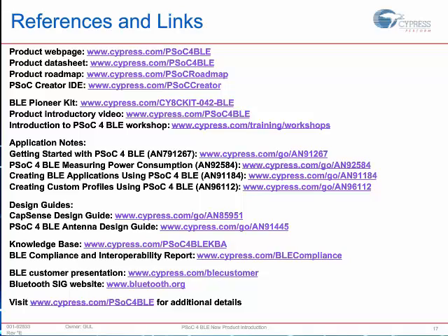And that's a really important feature in several of these Bluetooth products because once I deploy my product in the market, I'd like to be able to wirelessly bootload it or wirelessly upgrade its firmware and provide new features or functionalities or bug fixes to my customers. So the 256K is extremely useful for that.